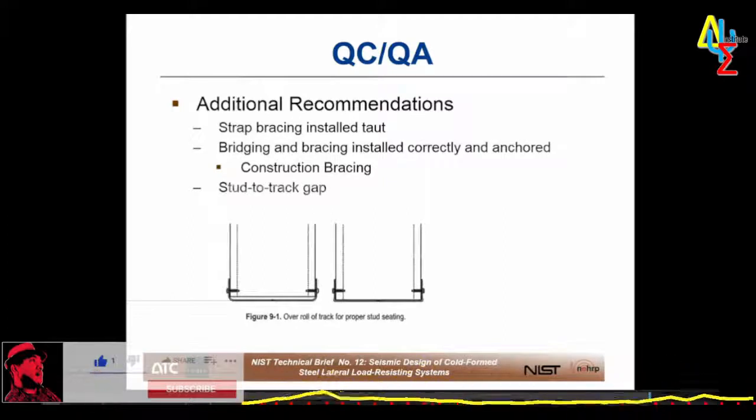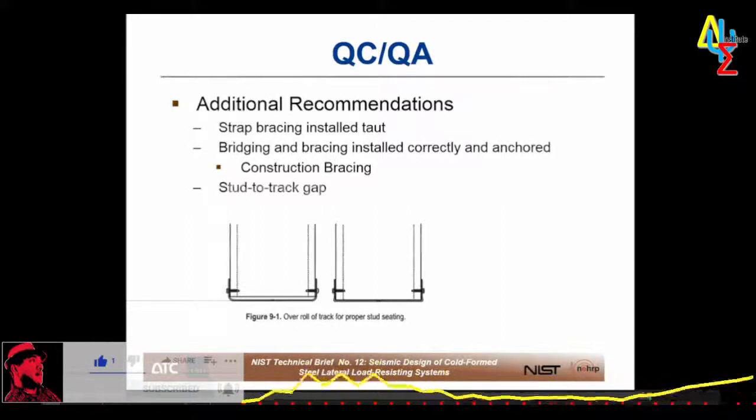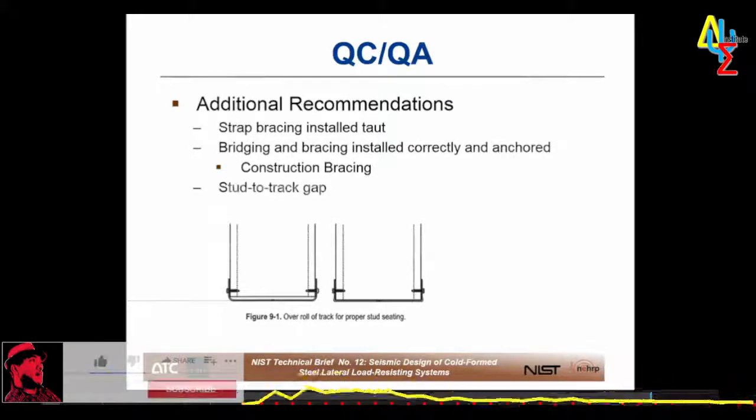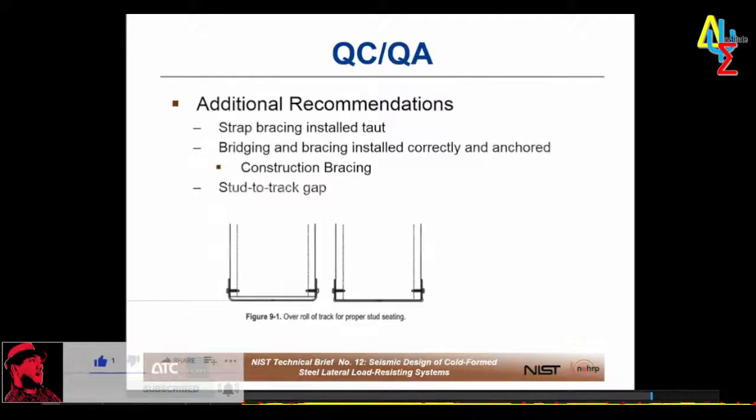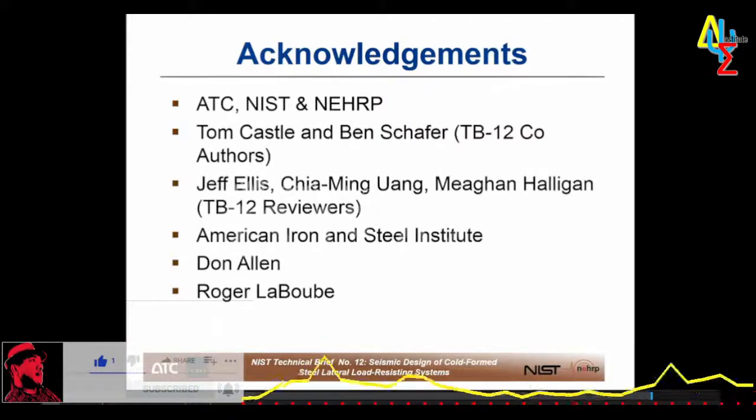And the stud to track gap is limited to 1/8 inch in S240-20 for 54 mil and thinner thicknesses. And for heavier framing, the designer needs to specify the gap. And that is all of the technical parts of our presentation.